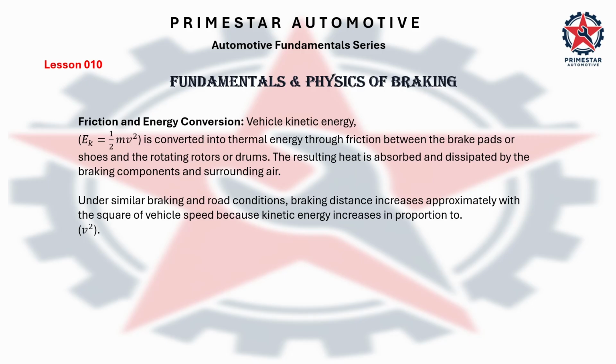Under similar vehicle braking and road conditions, braking distance increases approximately with the square of the vehicle's speed. Therefore, if the vehicle's speed doubles, the kinetic energy that the brakes must absorb becomes 4 times greater, and the braking distance may also become approximately 4 times longer.